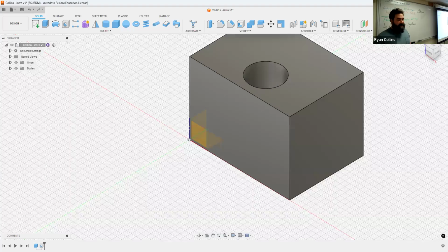At the very bottom is a history slider. It will save progressively, linearly, the history of what you are doing, usually. What I mean by that is some elements, like in sketching, it will not save point to point. But when you're making major changes to objects, it will save it, because you can't really make saves for each little thing. You can always go Control Z, Control Y, or on Mac, Command Z, Command Y to go back and forth, but otherwise it saves it that way. You can go back and forth in time on that too. Pretty neat. And you can always add something in between if you need.